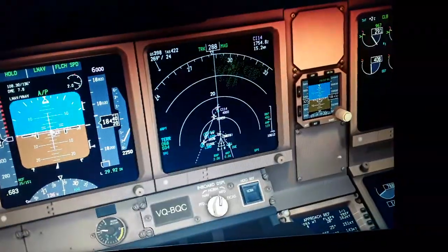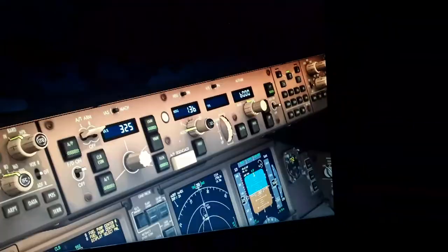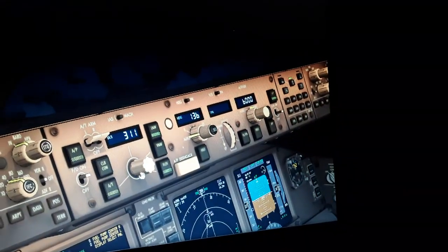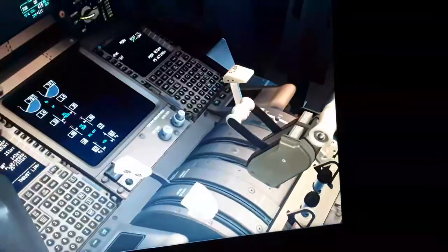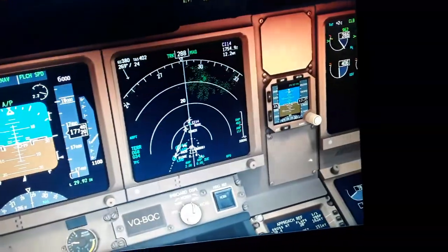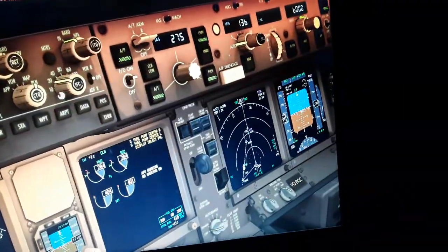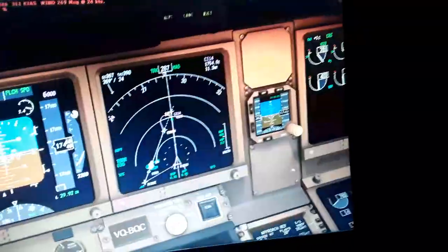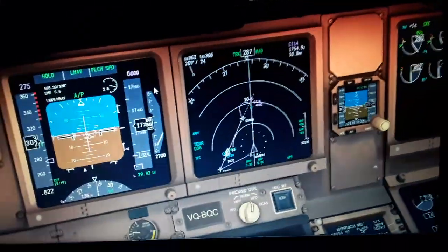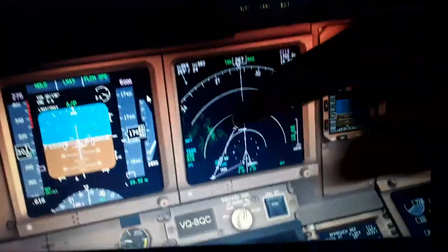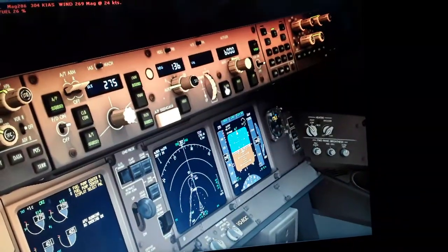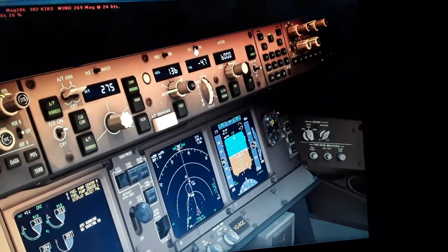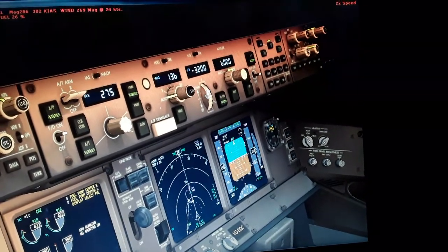15 nautical miles away, decrease maybe the airspeed a little bit, so making a safer approach into the runway. As we get closer, we need also to slow down a little bit as we're coming closer into the runway. Mach 0.62. You can see the rate of descent 2,000, 3,000 feet per minute. Select the VS, the vertical speed.